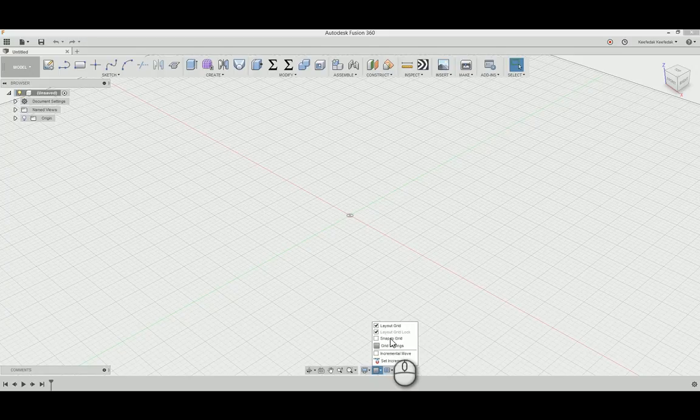Yeah. What is snap to grid? Oh, it's like when you move something and it'll snap to those little points on the grid. So if you want something to be 3.13 inches, it won't let you. It'll snap to 3.15. Okay. So you're going to just turn it off because it's so annoying for a beginner, unless you have tolerances and you're an engineer and you want things to always snap. And also turn incremental move off as well. Okay. That's good.